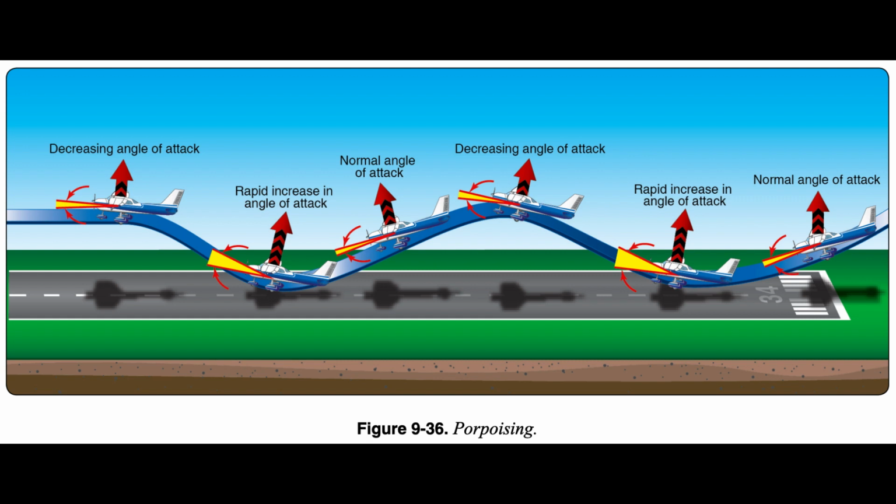airplane aloft again. The corrective action for a porpoise is the same as for a bounce and similarly depends on its severity. When it is very slight and there is no extreme change in the airplane's pitch attitude, a follow-up landing may be executed by applying sufficient power to cushion the subsequent touchdown and smoothly adjusting the pitch to the proper touchdown attitude. When pilots attempt to correct a severe porpoise with flight control and power inputs, the inputs are often untimely and may increase the severity of each successive contact with the surface. These unintentional and increasing pilot-induced oscillations may lead to damage or collapse of the nose gear.